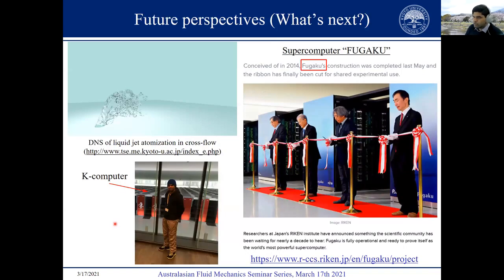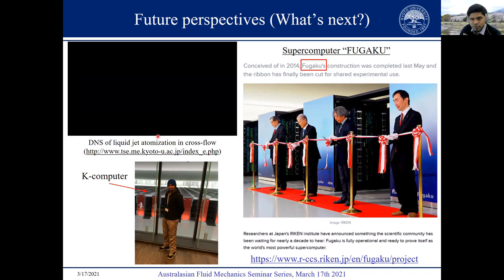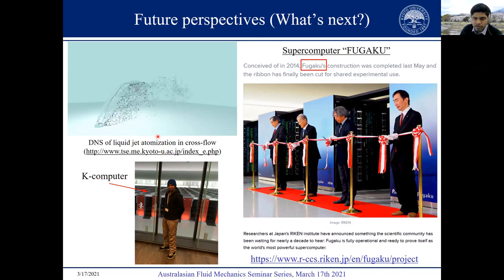Okay, so before I end my talk, I would just like to give you some future perspectives. In this work, our main objective was to investigate the dependence of heat loss through the wall on the fuel injection velocity. And we attempted to elucidate the relationship between Nusselt number and Reynolds number relating to wall heat transfer. However, the fuel injection velocity is not the sole parameter that will influence this phenomenon. There are several other parameters, for example, the operating pressure, temperature, bore size, nozzle diameter, radiative properties of the wall surface itself, the angle at which the spray impinges on the wall, and so on. So there is more work needed to develop robust and improved correlations for these wall impinging spray flames, so that we can use them for accurately calculating the heat transfer coefficient in CI engines.